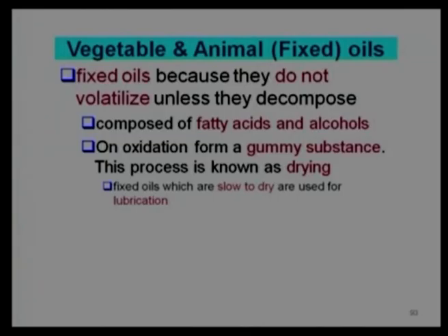And as I mentioned earlier, they are made of fatty acids and alcohols, or consisted of alcohols and fatty acids. Fatty acid work as a boundary additives. Now, what is the problem with their oxidation? They make a gummy substance which will stick to surface, reduce clearance. When the clearance is reduced, operating condition will change. If operating condition will change, it may bring much more difficult situation.